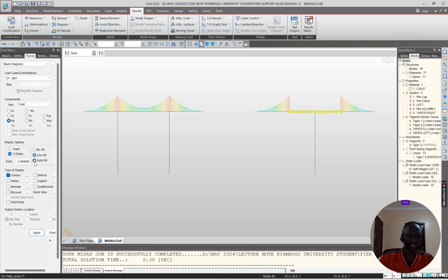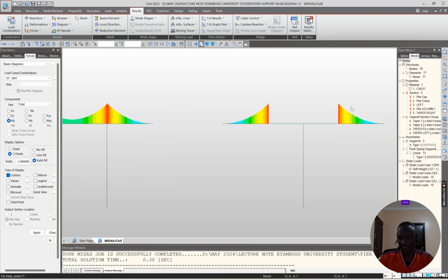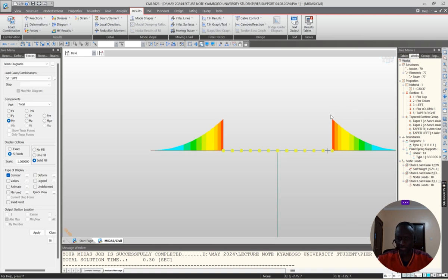That is what normally is there. That's how it's supposed to appear here. So you can see over this support you have stresses, and you cannot have a moment going up here, because the whole of this is like one deep wall, monolithical with the pier cap. So this is it. Your worst pier moment should be away by 3 meters. That's the moment you use for design.